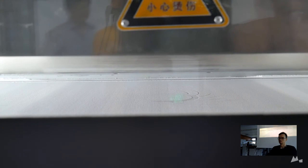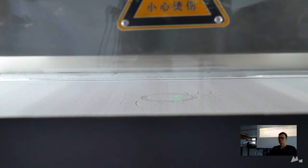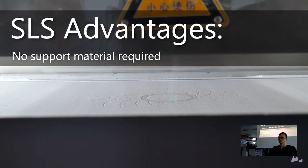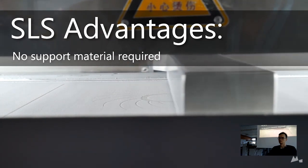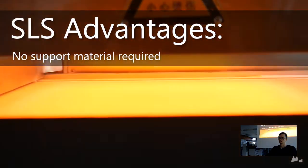But what are the advantages of SLS 3D printing? Well, it has a few key advantages over regular desktop FDM, one of which being you don't need support material. Being a powder system, the powder that isn't sintered actually acts as a support for the part as it's formed in the build chamber from the bottom to the top. The platform actually starts here and drops down.